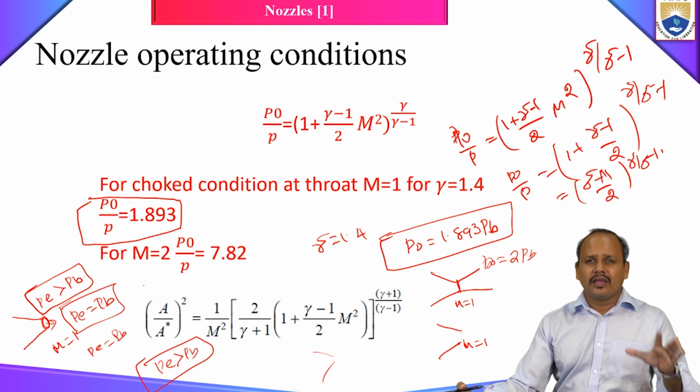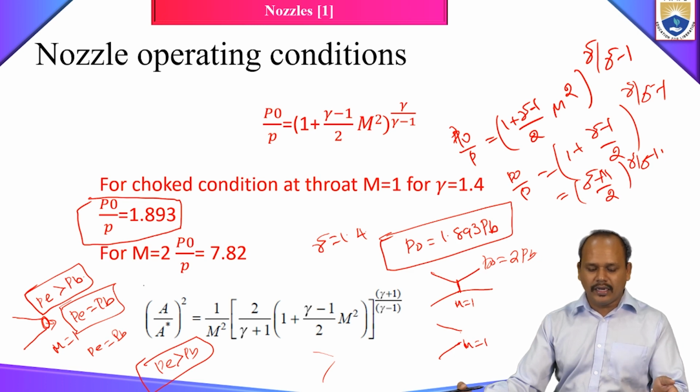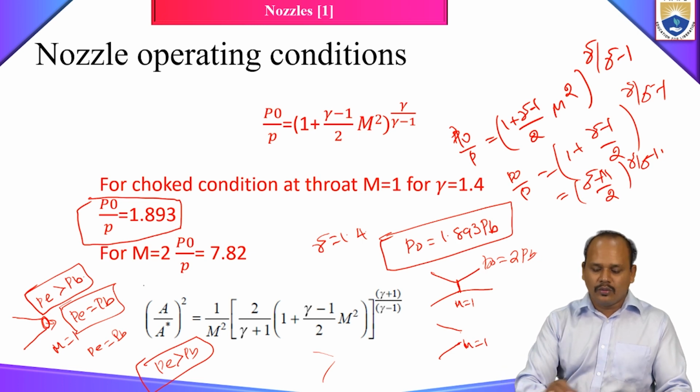We already know in a supersonic flow, any change of state will always occur through a certain type of wave. Okay, so here, since your pressure is more than your back pressure, you have to reduce your pressure in order to attain the equilibrium. So what happens is that you will have the expansion fan formation at the nozzle exit. Okay, so once the expansion fan forms, your flow pressure will be reduced. So there it will try to attain the equilibrium.